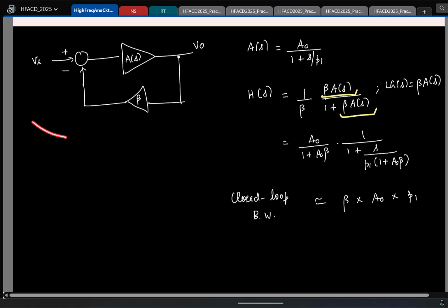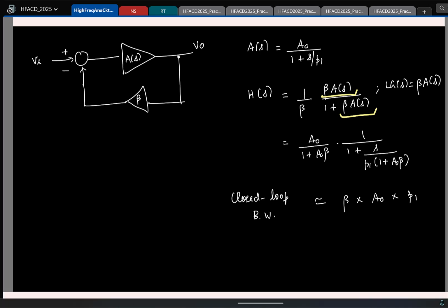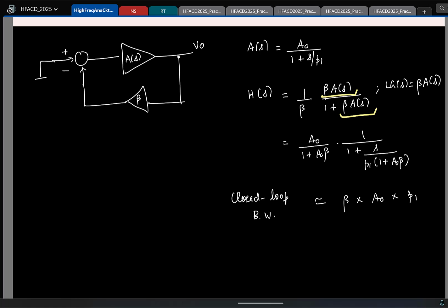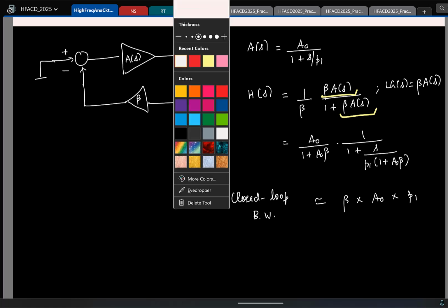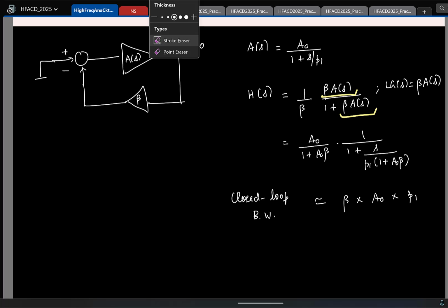And if I give a feedback loop like this, how will you calculate the loop gain? You break the loop, but what do you do for the input here? Yeah, you make the input 0. It's a voltage source, so it becomes short, and then you can break the loop. This is an ideal block diagram model, so you can break the loop anywhere without any consequence.